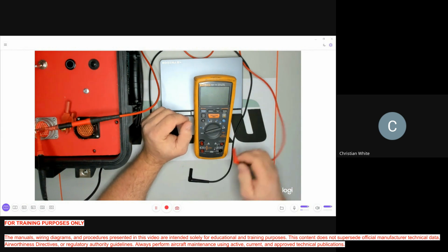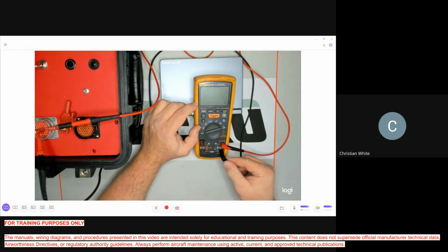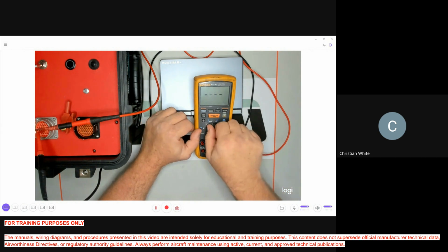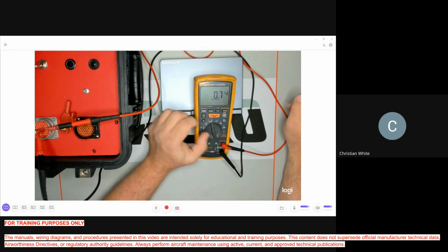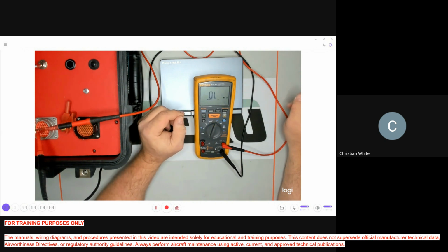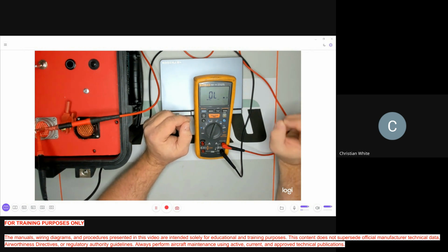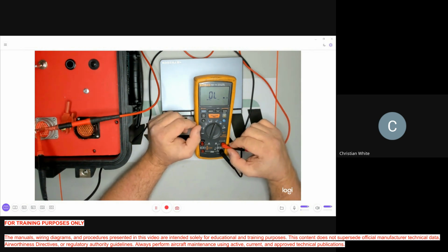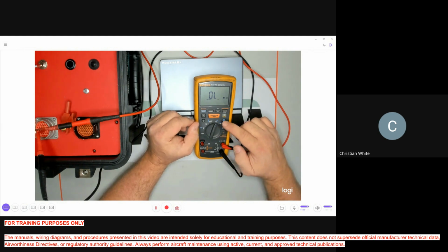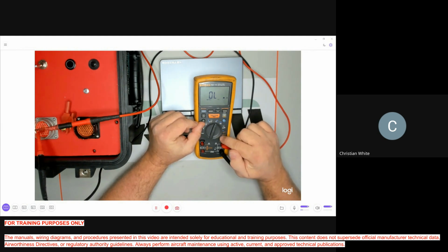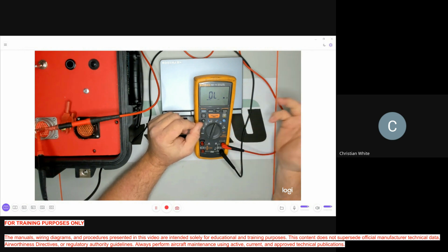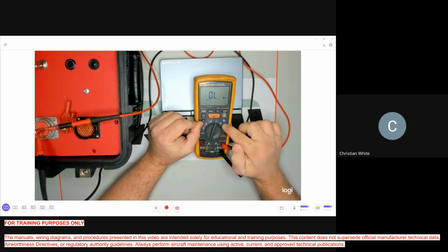Okay, multimeter side, you would put your leads in on this side, turn it on, go to whatever function it is. Something I usually do is I go to ohms and I check the resistance of the circuit that I'm going to test. So I do two checks, especially when I first start testing. The reason we do this is if I see anything in here at all, I've got to really make sure that the wire I'm going to test is not going through a component somewhere, such as a box or what have you, because you really shouldn't see anything involved here at all.